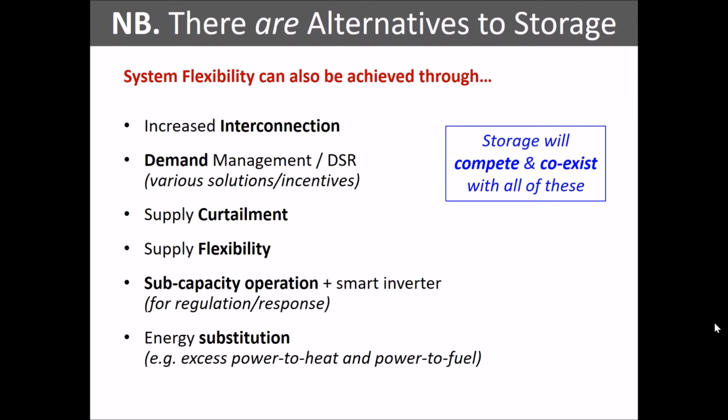Let's have a look. Reduction in grid capacity has only really been mentioned, not entirely explained yet. Is this from its ability to provide reactive power support or reduction in peak transfer capacity? Okay, yeah. Obviously, when we're talking about grid capacity, it depends where in the grid we're talking about. If we take something like large-scale wind power plants, they tend to be built in places away from centres of demand, because it tends to be windy places where people don't necessarily want to live. So you can end up with quite a lot of supply capacity built in areas of the grid where the grid, if you like, is inherently weak. It's not been built for great big power plants. It's in more remote regions.